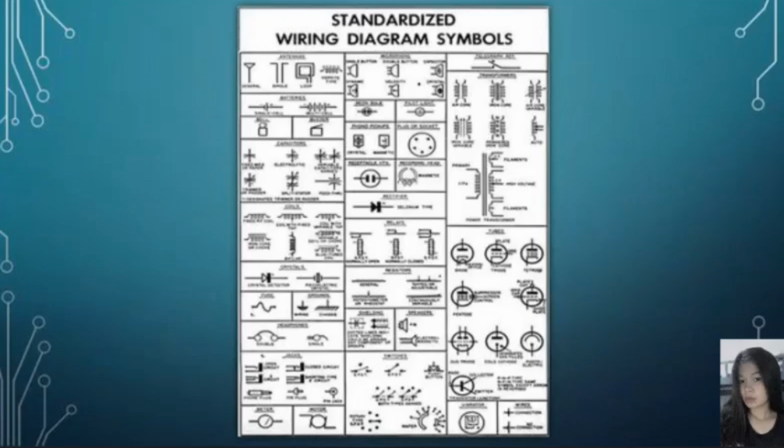It is important to distinguish between these two because the polarized capacitor needs to be placed correctly according to the plus sign. Resistor. The schematic symbol of the resistor is drawn in two different ways. The American style resistor is drawn as a zigzag, while the European style resistor is drawn as a rectangle. Transformer symbol. The symbol of the transformer looks like two conductors with something in between them.